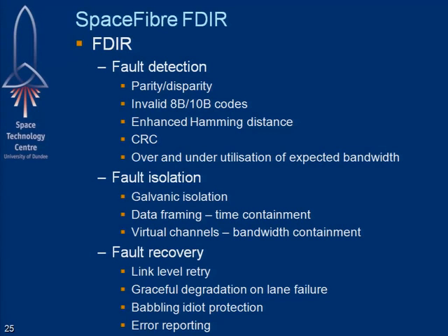So that means when we send a frame of information across the link, we wait for an acknowledgement to come back before we release that from the transmit buffer. So this retry mechanism is very effective. We've actually designed a technique whereby we don't use timeouts for this. The typical idea is you'll send your frame and you wait for the acknowledgement. If you don't receive the acknowledgement within a certain time, then you time out and resend that frame again. We don't actually use timeouts. We've got another mechanism that's used to do this.